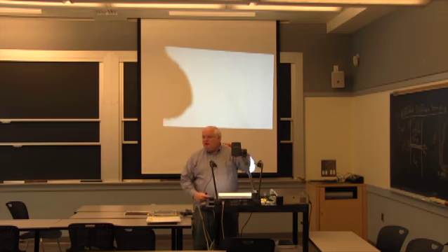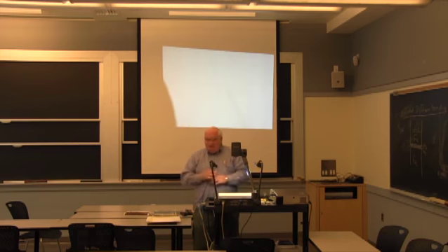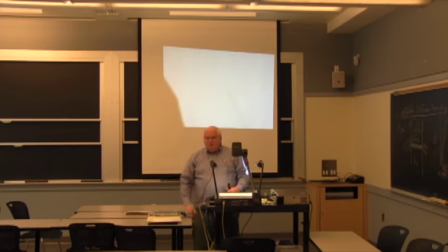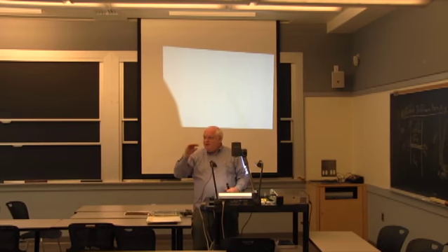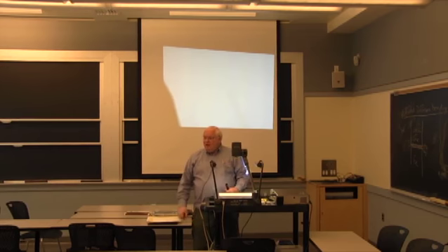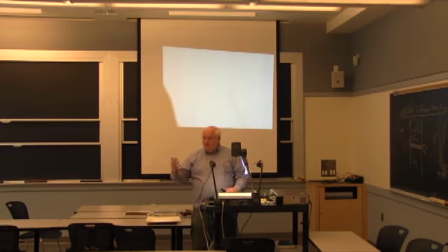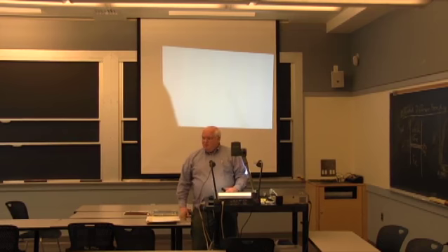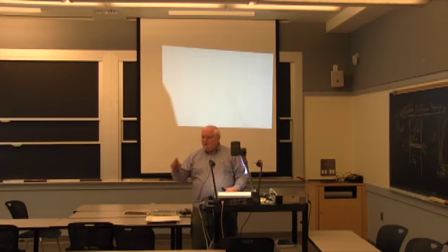So it turns out there is a natural breaking point between soldering and brazing. There's a certain class of alloys that melt below 400, and a certain class that melt above 500. And 450 is the happy hunting ground between 400 and 500, and that's where the International Institute of Welding defines the difference between soldering and brazing. So there is actually a scientific foundation for it, because nature forgot to give us something that melts in that range.